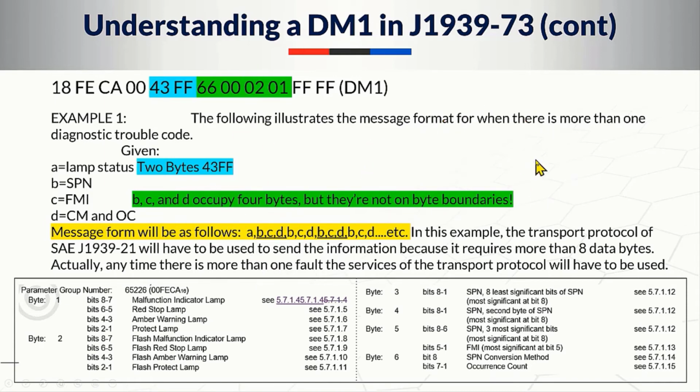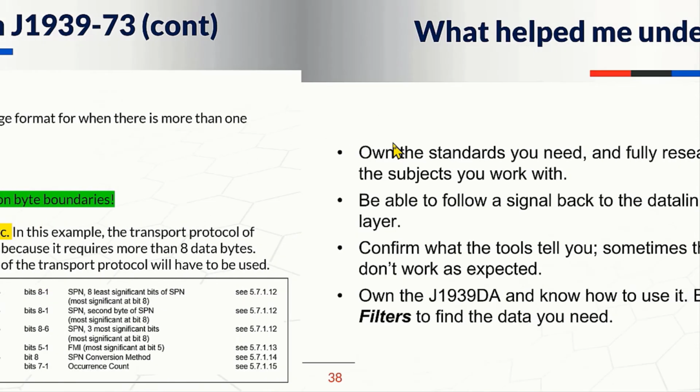That shows you when and how transport protocol is used, how to read a DM1, how to use this sequence to read a diagnostic trouble code, which appears in many other diagnostic messages as well. There's a lot in there. So DM1 is a variable length diagnostic message.